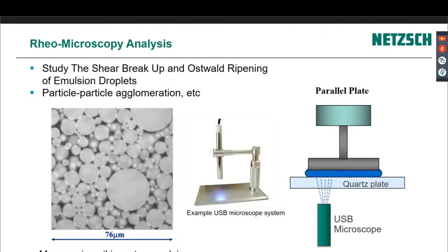And then afterwards you stop shearing it, and you can see if the particle size has broken down to very small particles if you shear it fast enough, or maybe it started to break down that emulsion. Maybe it's just now homogeneous or whatever. So you might invert the emulsion if it was of the wrong concentrations and things like that. So you can see stability. You could obviously do temperature ramps with this as well.